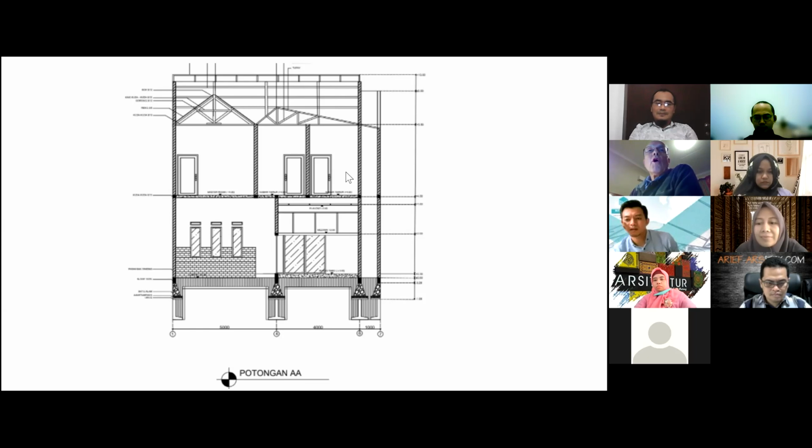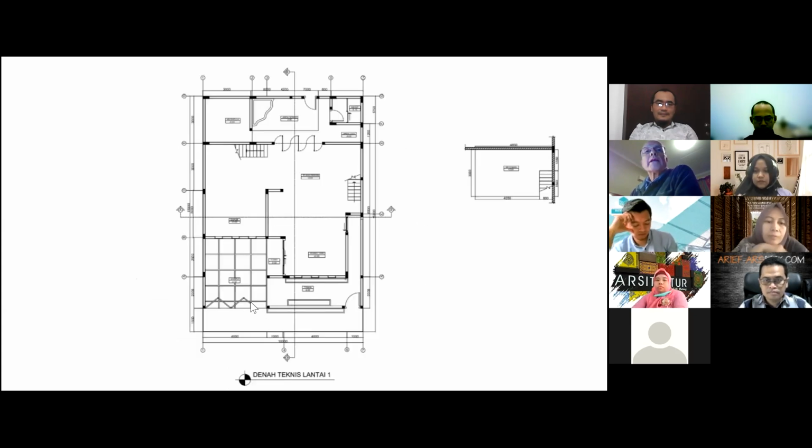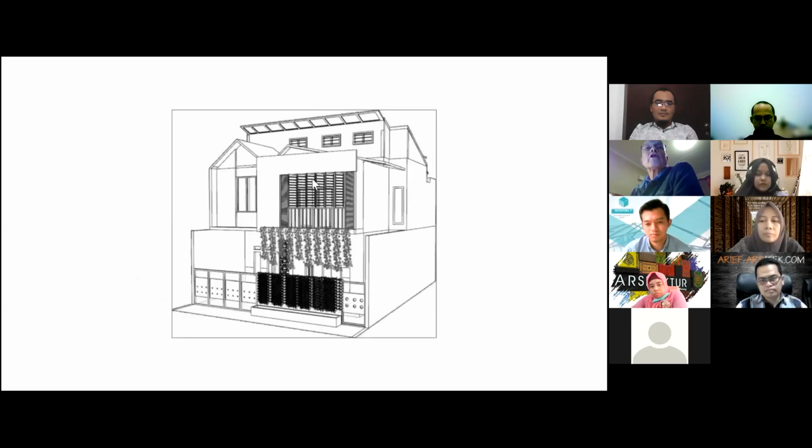Right, well, if we want to make this building safe in earthquakes, we've got to provide more resistance in the X direction. Now, because of the program of the building, you can see that the student has got a lot of glazing, a lot of windows at the front of the building. And so clearly it's not possible for us to use solid walls to resist earthquake near the front of the building. In order to maintain the natural light entering the front of the building, we're forced into using moment frames to resist earthquake.